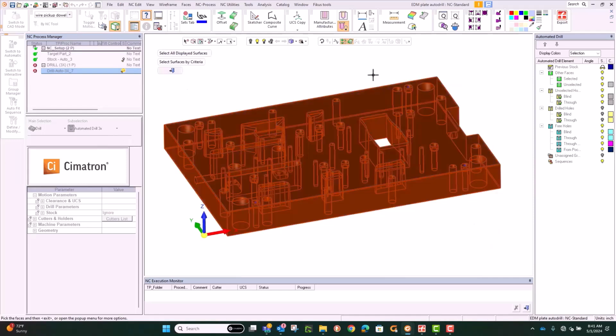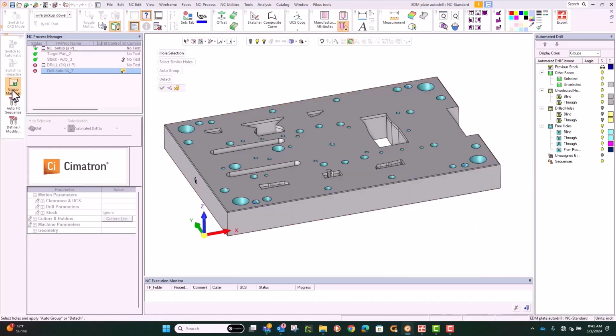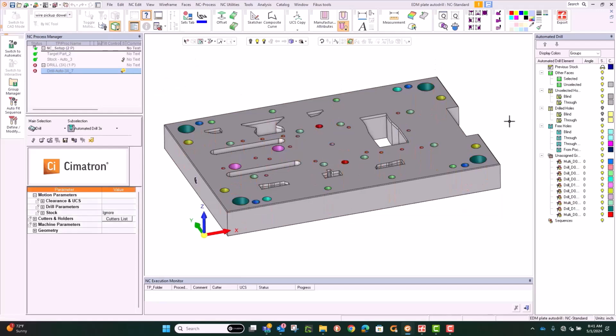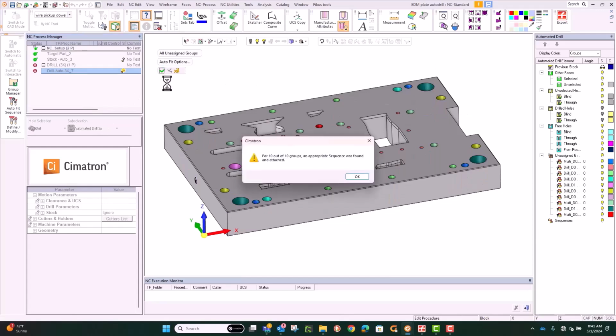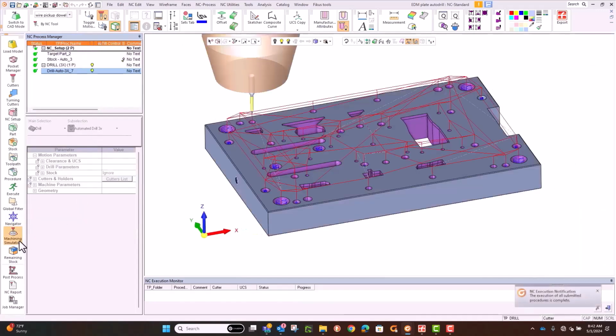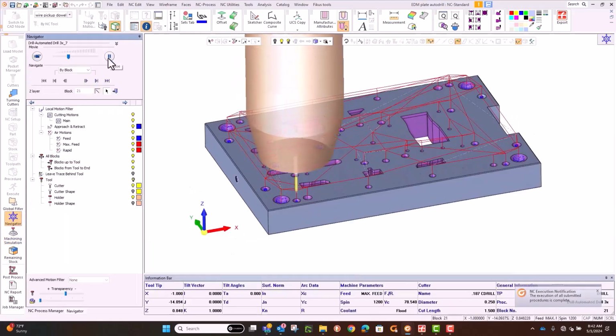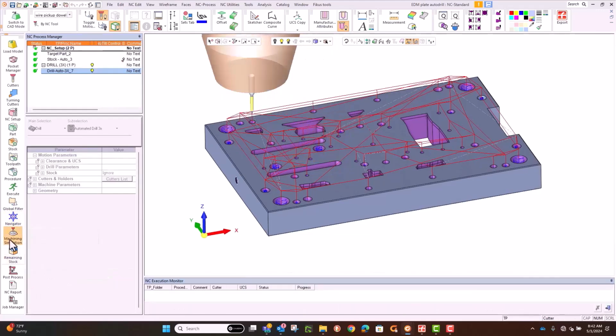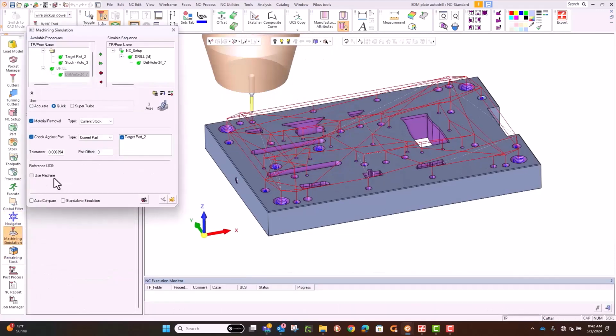Now we're going to target the holes. There's a lot in this when you think about what's involved with holes. Set this up as a 3-axis drill program. Tell the system, go find the holes. There they are. Now group them. So it groups them according to the size, diameter, configuration. Is it counterbore? Is it through hole? And then we'll run it through our list of sequences, different operations, like a library of drill hole strategies.